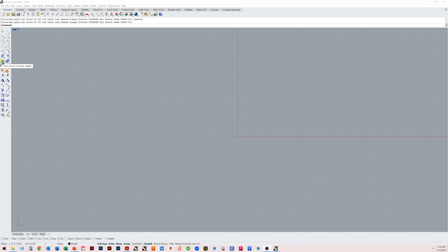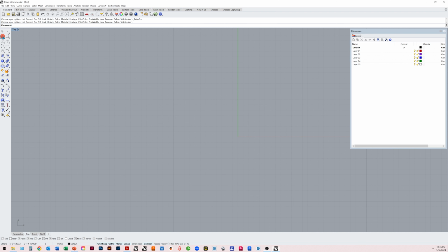Okay, now we are going to start in with drawing lines. As we mentioned before, we have the command up here, the polyline. So let's just click that button. We could alternatively have typed polyline in. And then let's look and see what the mouse does. If you look, you can see that the mouse has a little dot in the middle that's bouncing around this grid.